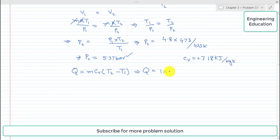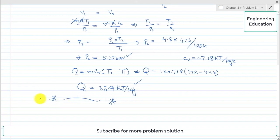so it will be 0.718 into the value of T2, which is 473, minus the value of T1, which is 423. So simplifying this, the value of Q comes out 35.9 kilojoule per kilogram. So this is the value of heat added during the process, and it is the solution of problem 3.1.